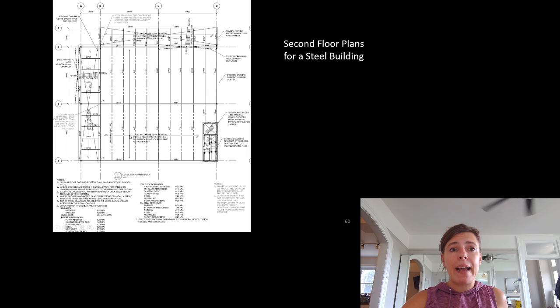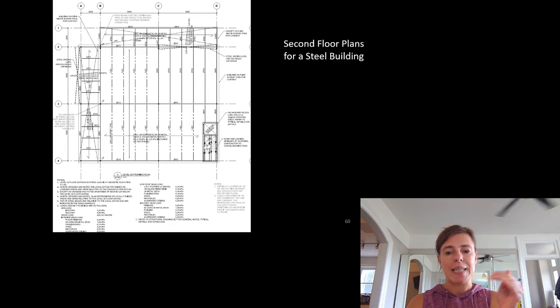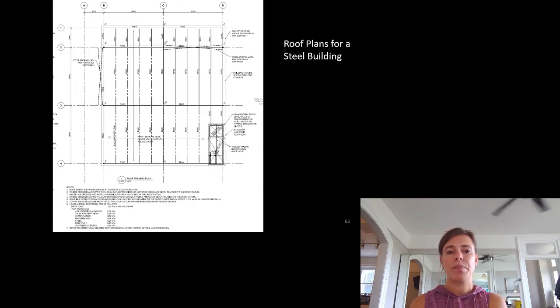These ones here look like they're just picking up our deck that spans in that direction, so we'd probably call them purlins. This beam right here looks like it's just picking up purlins or open web steel joists, so I'd probably call it just a regular rolled beam. Again, that's going to matter when we start to talk about our sizing guidelines in a few weeks.